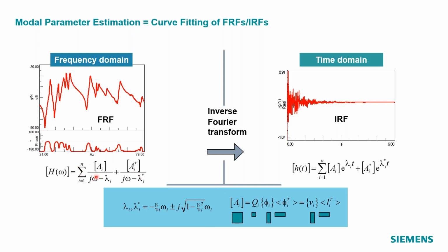That's quite nice about it, because after the curve fitting, we don't end up with a mathematical equation. We end up with parameters that have a clear physical meaning: damping, frequency, mode shape. These are all very meaningful parameters that give a lot of insight into the structure.